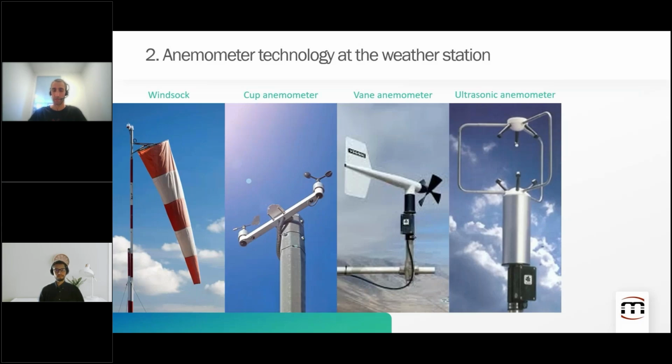It's not for safety. Usually with this kind of cup, you have a weather vane to catch the wind direction. This technology is the standard for wind assessment for wind energy. When we conduct wind resource assessments, we use this kind of cup anemometer. Not the last one yet, the third one is a vane anemometer. It looks like a small airplane. Like the cup anemometer of Robinson, the axis is horizontal.